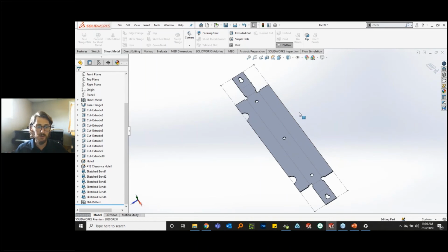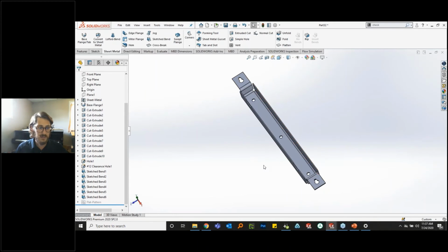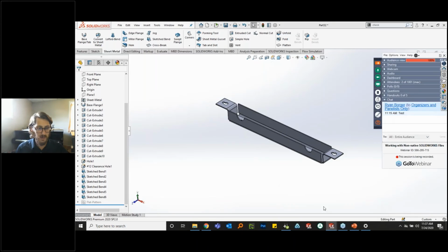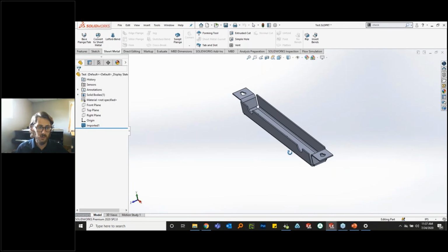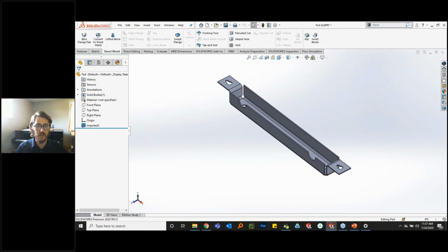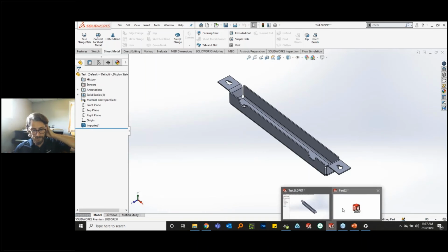And if I'm importing this model in for the first time and this was my end goal, I've now reached it in a matter of minutes without having to recreate the model, go through anything hyper complex. If this were to fail and not create a flat pattern that I was ideally after, that's okay. Because as I had mentioned, when I highlight down here, our original part is still here. We still have the ability to go back through and try to recreate some of the feature recognition from this model that we've already confirmed that the import diagnostics and the check entities came through, suggesting that it's healthy, ready to go imported CAD data.